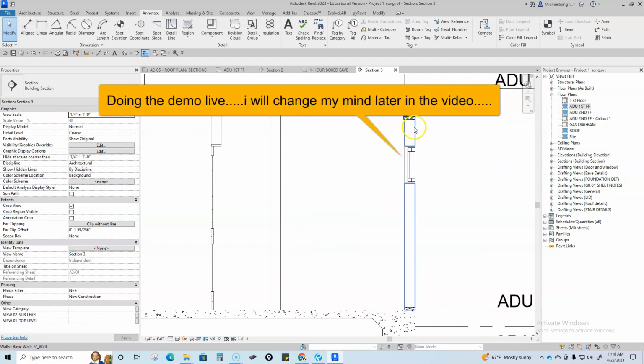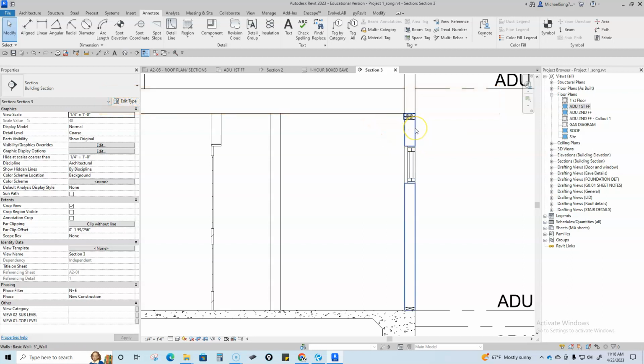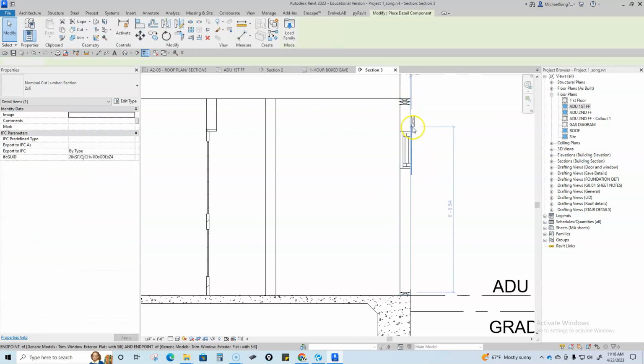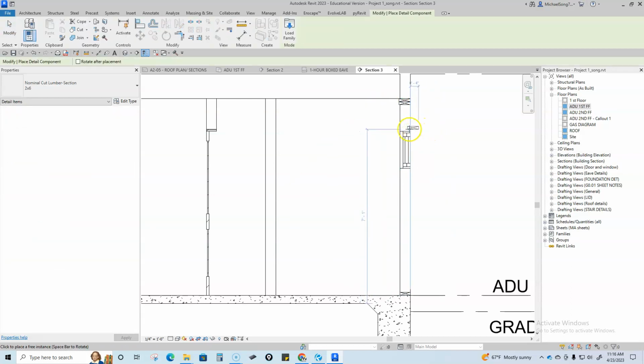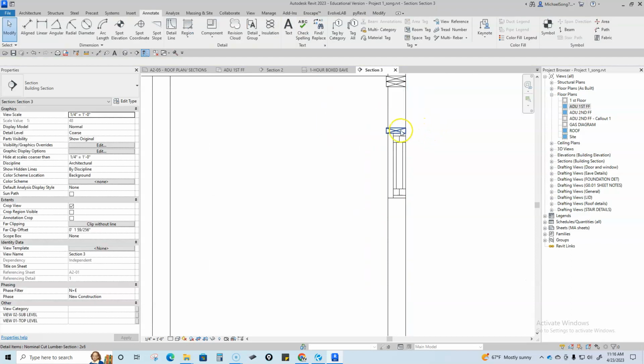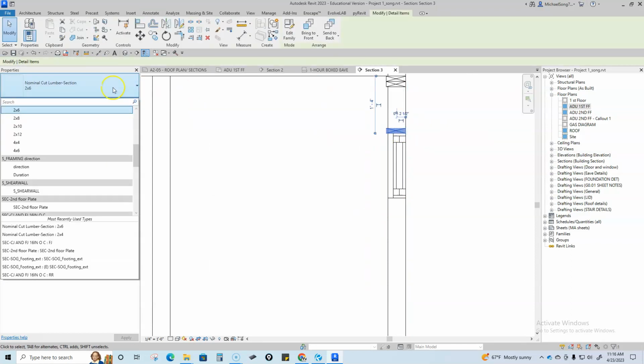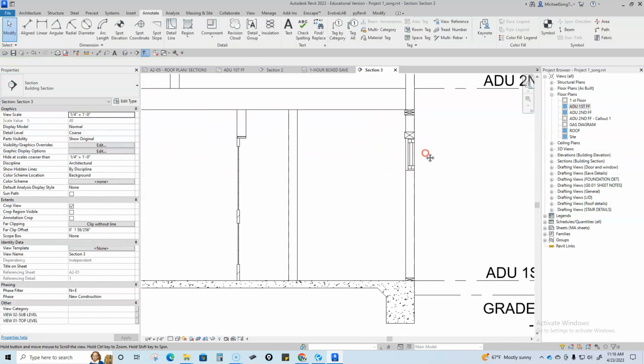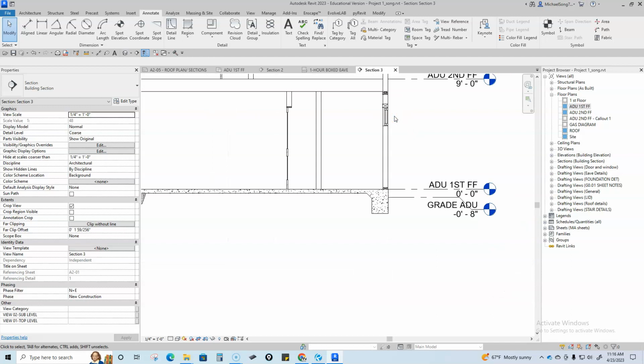Okay, so I have 2x6, and then I have my 2x6 wall going all the way up, and that's basically your wall assembly. And then when you have a window, you're going to need a header and then a sill on the bottom of the window. So again, I'm going to take that, CS for copy style, pop that in, but headers are usually going to be 4x, so I'm going to use a 4x6. So here's my header.